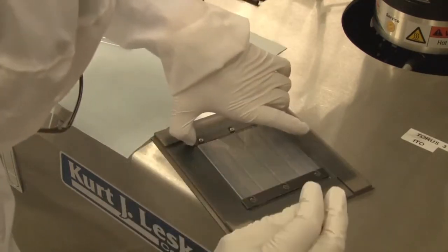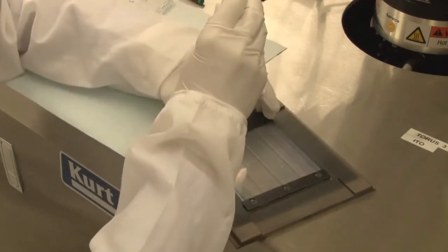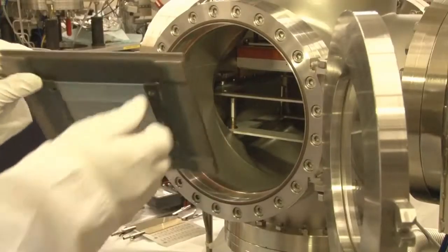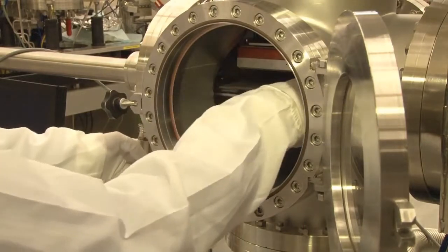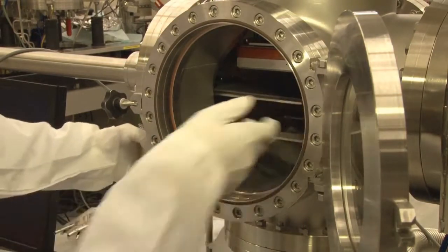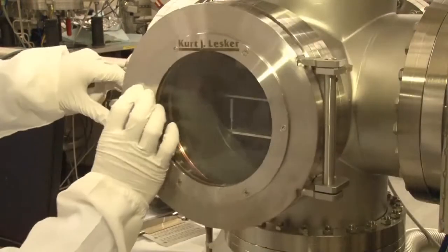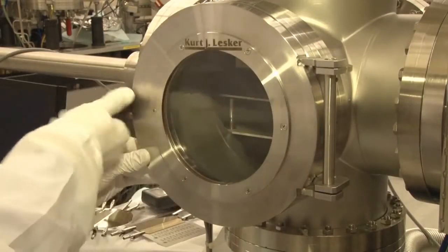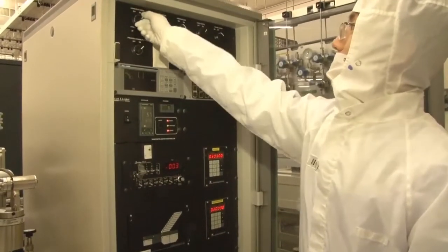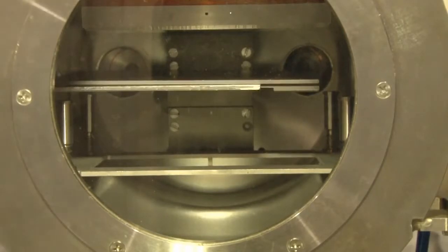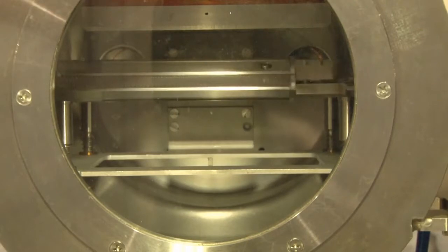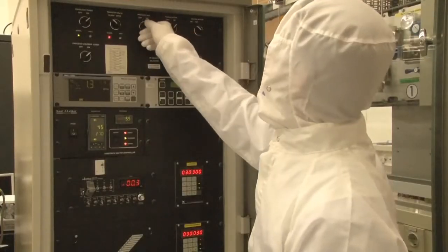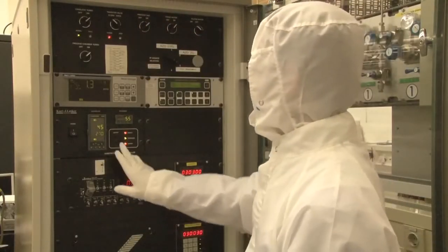In this movie, we deposit a thin zinc oxide layer on top of the Asahi substrate to protect the tin oxide from the next processing steps. The substrate is mounted on a sample holder and put into a load lock. A load lock is a chamber in which the substrate is brought under low pressure before it is moved into the processing chamber. This avoids the processing chamber being contaminated with various unwelcome atoms and molecules present in ambient air.